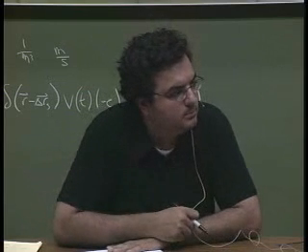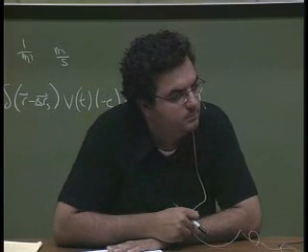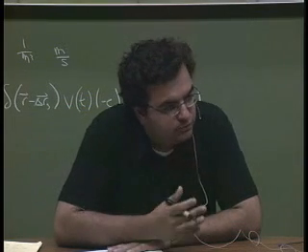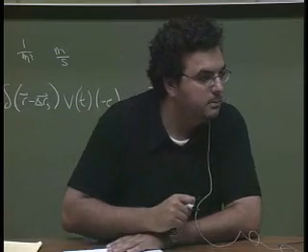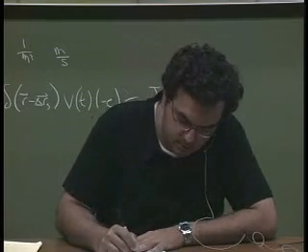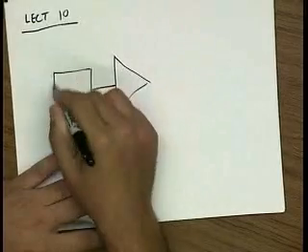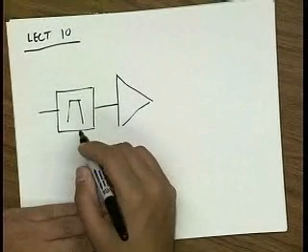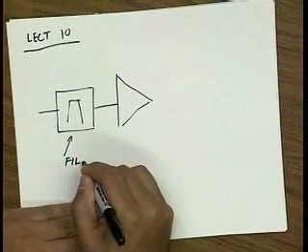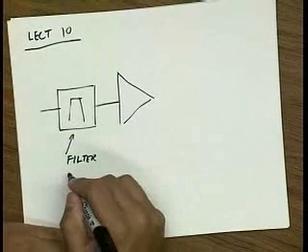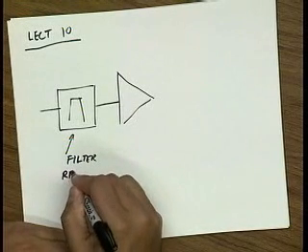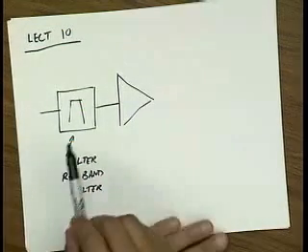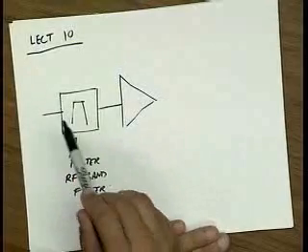Last time we talked about jamming. So the question is, can filtering help solve the problem with jamming? Certainly it can help, right? Let's draw a picture here. This is my LNA, and I put a sharp filter in front of it, and this is the band of operation. This is basically called an RF band filter. This will help with out-of-band jammers, right?